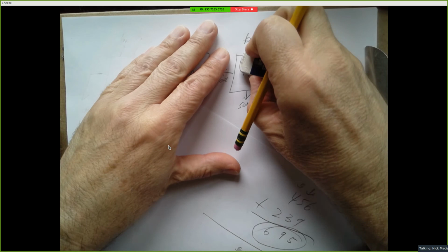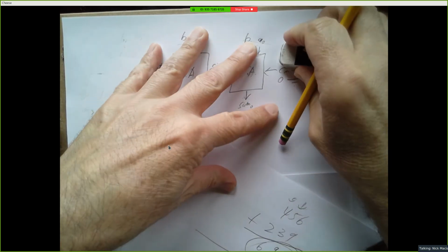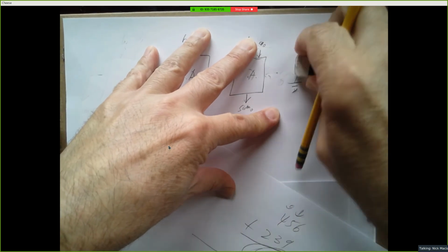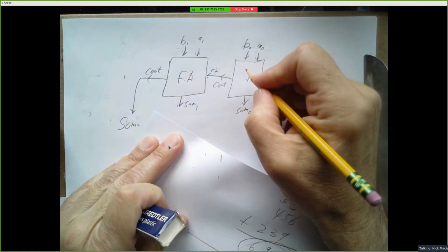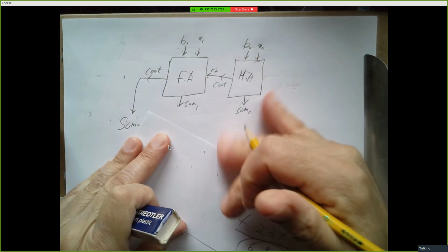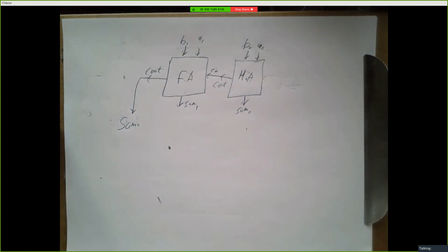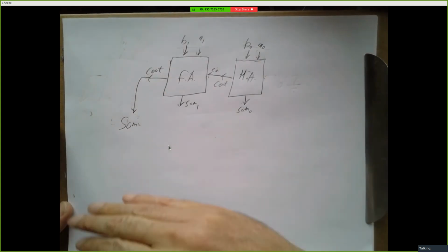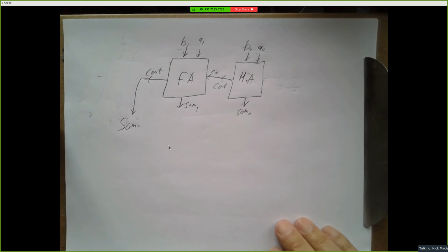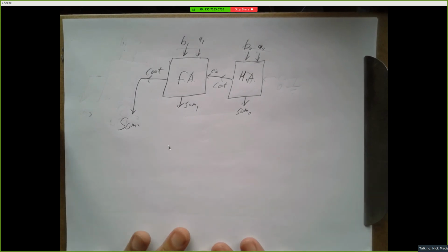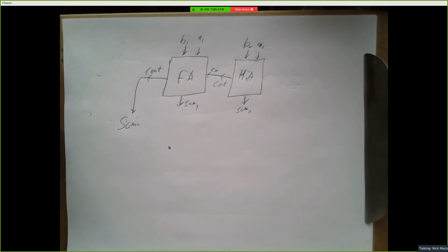And so we can replace this first full adder that we set the carry in to a 0 with just a half adder. And so there's the other way to build a 2-bit adder. And this is a whole lot less circuitry than just working from the straight truth table with 4 bits in, 3 bits out. Now it takes a lot of analysis to get here, right?